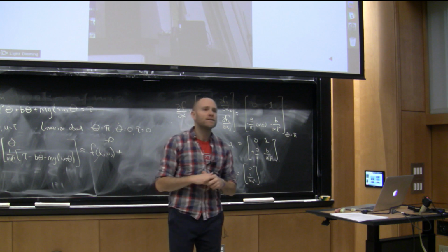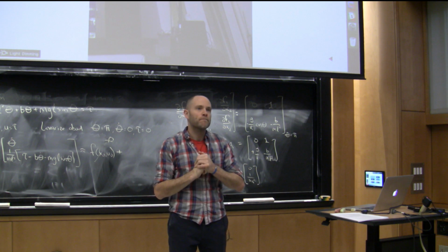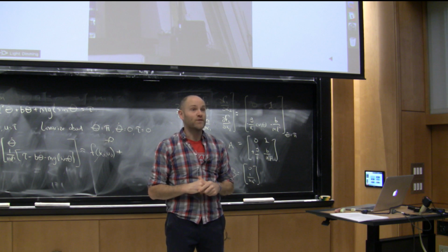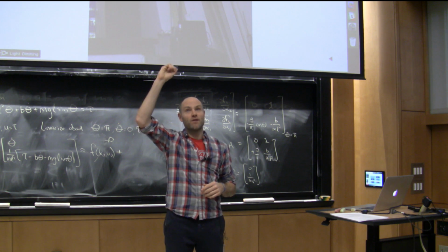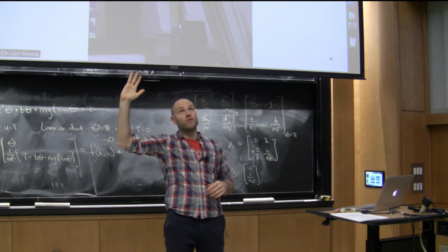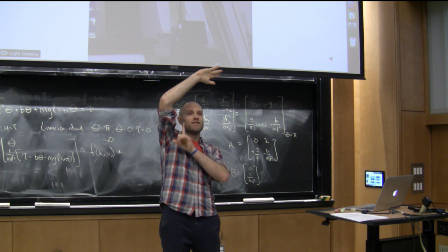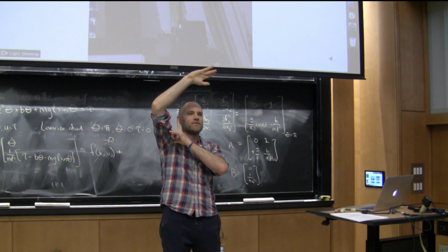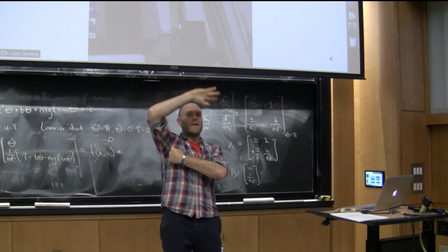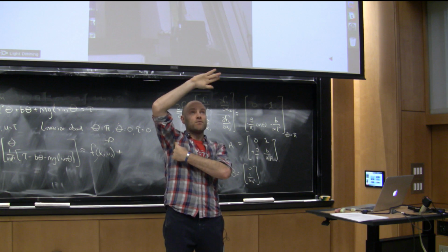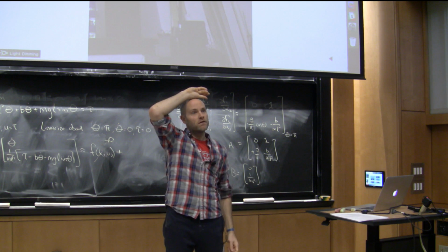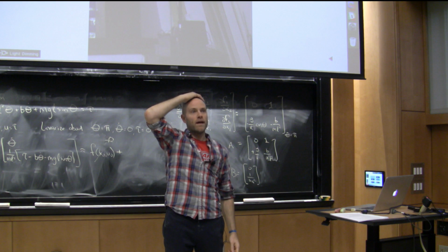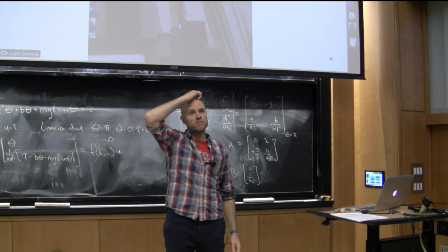So would you expect this thing to be a lot more stable, trying to balance in this position? Yeah, I think that's a really good question. You could stabilize in some other configuration, as long as the center of mass of the two links is somehow above the pivot. There is a manifold of solutions that you could stabilize. If you picked one of those, you'd be stabilizing with a nut. I bet you could do that better, because you'd be sitting on one end of the actuator.